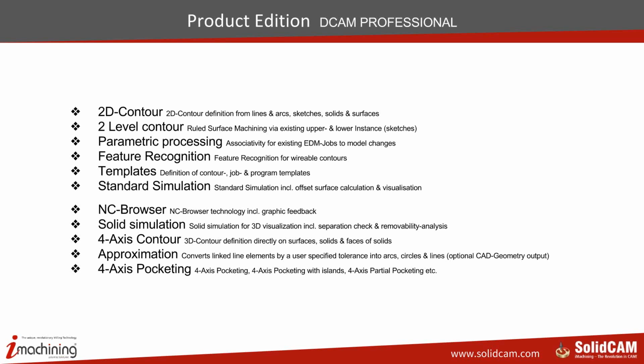The next feature is 4-axis pocketing. This is a very nice feature which allows us to create slug-free, let's say, dies. And therefore, we will not need an operator to remove slugs. Our machine will not stop if we have a slug to put magnets, etc., and we will create a much faster job than the regular contour programming.